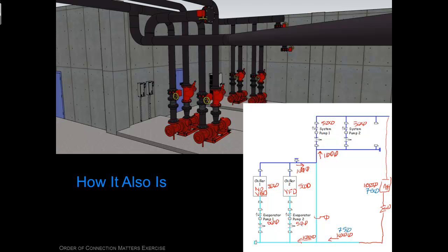Now, when we get to this T, we still have two pumps running. Okay, and because we picked it that way, the head on those pumps isn't varying no matter what's going on out here. They're still going to take 500 GPM each, so there's still going to be 1,000 going this way. So if 750 is coming in and 1,000 is going out, and I'm not creating or destroying water in this pipe, the only way I can get that extra 250 is to have it reverse and flow backwards through this pipe.